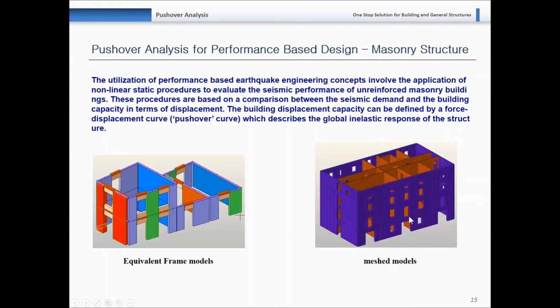Although the meshed model gives accurate response and cracking pattern, there is a requirement of high time cost, and you need a lot of computational skills, which is not always available, or time is not always available with us. So we shall look into the equivalent frame model, which shows essential characteristics of perforated wall response and can evaluate the key design parameters of ultimate strength, maximum displacement, as well as failure modes.